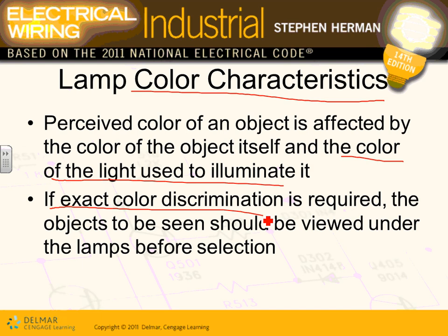But say you're working in a lab, like for example the manufacturing floor that we have, where they're working with chemicals. Wouldn't you think they would need to be able to see the color of the chemicals or the color of the labels on the chemicals? That's a major thing. That's a safety hazard. So color rendering index, if you're doing manufacturing, chemical equipment, nuclear, whatever, that's a big deal. Color becomes more important than seeing my car in the parking lot, so you need a fixture with a very high color rendering index. Remember, higher is better, but most expensive, of course.